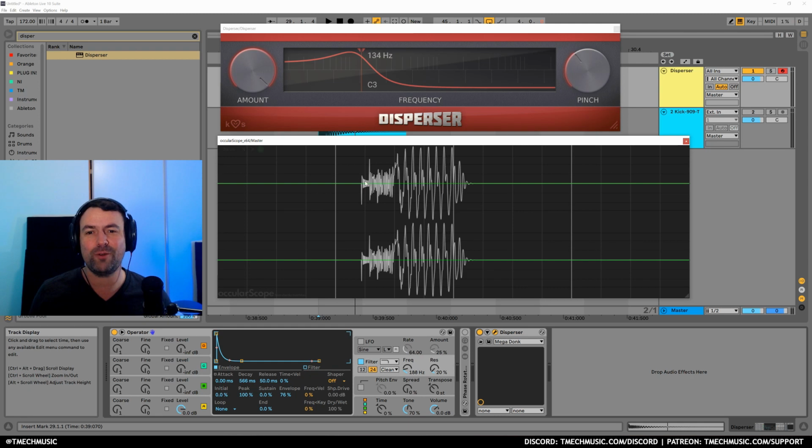So you can see that we get the high frequencies first, and then the bass tone is pushed out in time. So we hear the initial pluck of the bass really clearly because it happens before everything else, and then the lower parts of the signal come in. Disperser is doing that, and by modifying the frequency of the midpoint of the all-pass filters, we get different effects.